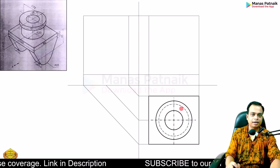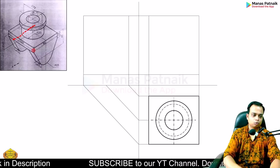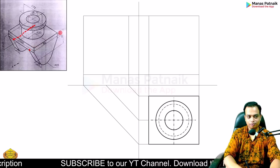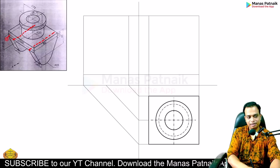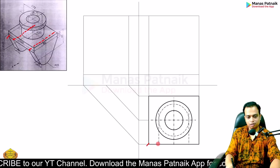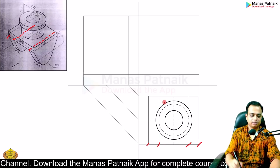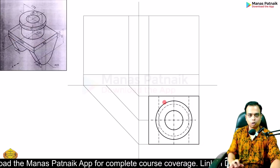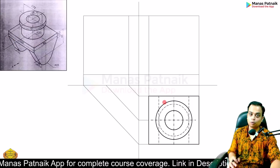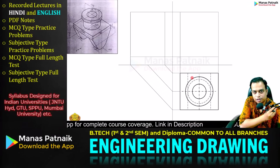One thing is left. There is a hidden edge. Which one? Here it is. Throughout the object, throughout this width, 90 millimeters. So 20 millimeters from here, 20 millimeters again from here. These are the two hidden edges represented by dashed lines. Top view is over. Now what shall we do? We shall go for the front view now.